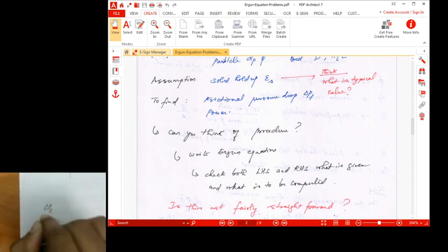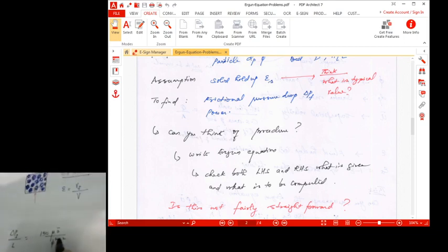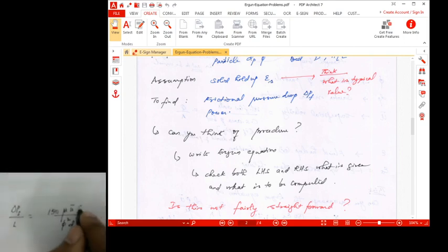So we have delta P_F, the frictional pressure drop per unit length, equal to 150 mu u bar by phi square dp square. Now, it's an easier way to remember. You just need to write first the viscous term. The viscous term is linear in velocity, and in the denominator it is the square of the linear dimension, in this case the particle size, and this will always have a cube of the void fraction or the fluid hold up, and in the numerator you will have the solid hold up, epsilon s, and the power on the epsilon is always the power of the particle diameter.